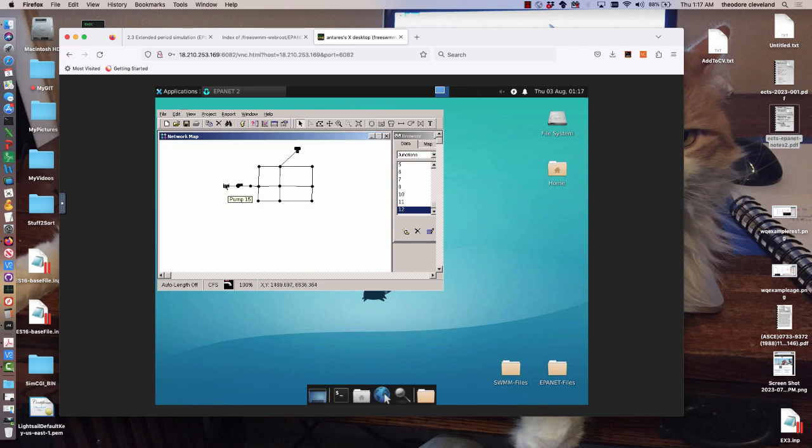So the top of the water in this reservoir is at the same elevation as the first node. So there's no natural way for the water to go into that network. We need the pump to force it into the network.